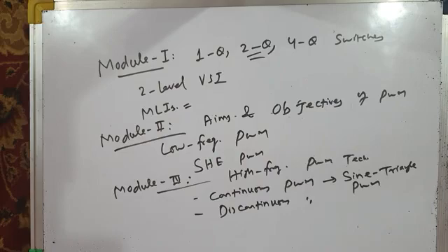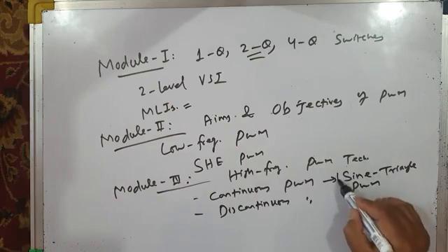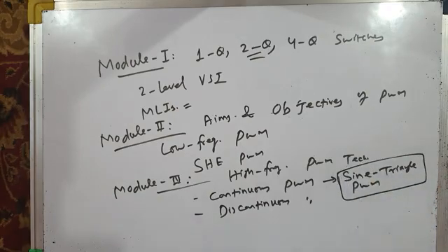In three phase PWM voltage source inverters also, we started with naturally sampled PWM or sinusoidal PWM, what we call a sine triangle PWM. Okay, we discussed it in great details. We discussed the harmonic spectrum and all that. And then I discussed with you the injection of third harmonic component, adding those to sinusoidal modulating waves and giving rise to third harmonic injection PWM technique. Okay, that was also a form of continuous PWM technique.